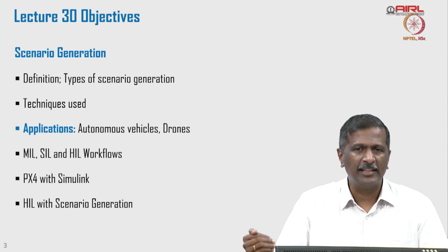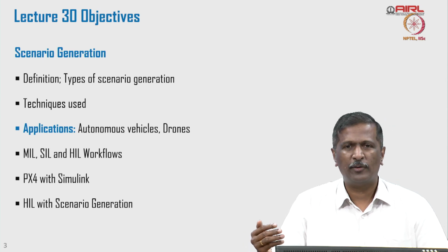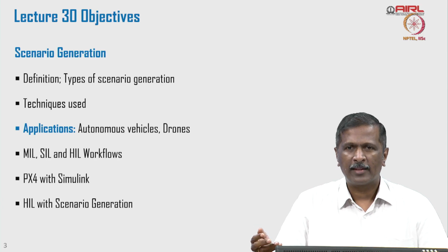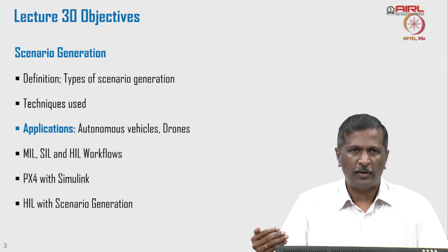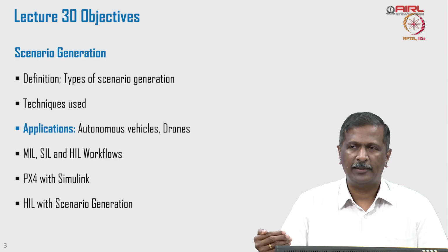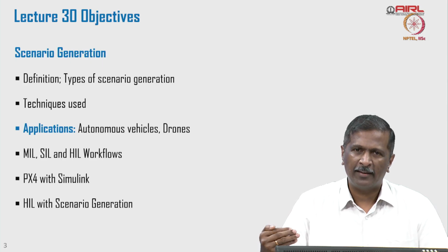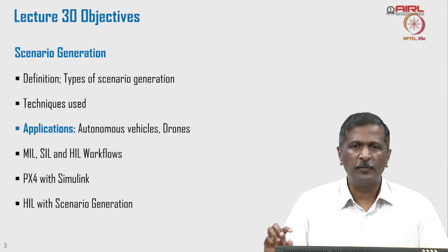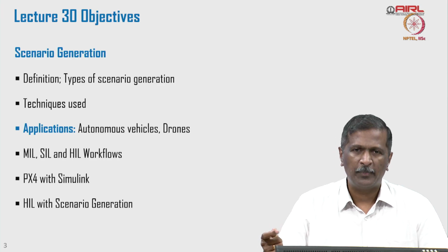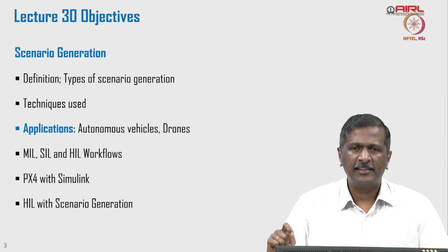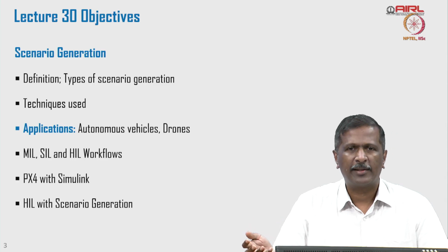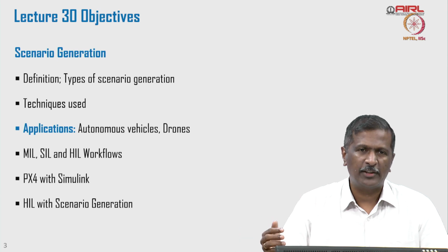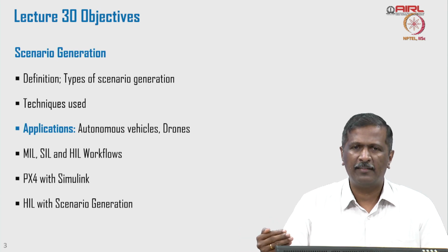It depends on the physical limitation of the vehicle. It's not the same for every system, right? If you are asking a drone to pitch forward to gain forward velocity and you are pitching at a very high angle, there is a likelihood of wind related uncertainty leading to instability and falling, right? So we need to figure out what the acceleration limit is, right? What kind of acceleration is possible for the drone to take care of. At the same time, it depends on what payload you are carrying, what kind of wind uncertainty you could have. So we have to verify everything.